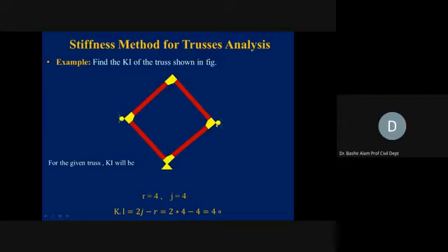From the right one, it can move in the vertical direction. So 1 degree of freedom from here, and from the left again, it can move in the vertical direction. So 1 from here also. The bottom one is not allowing any kind of displacement. So it means it is a 4 degrees indeterminate problem. This was the kinematic indeterminacy by observation.